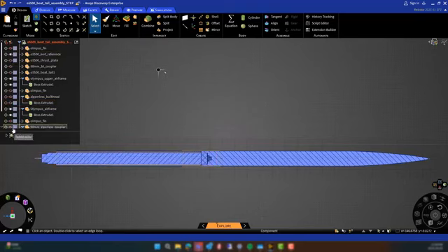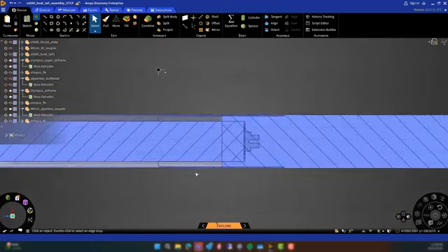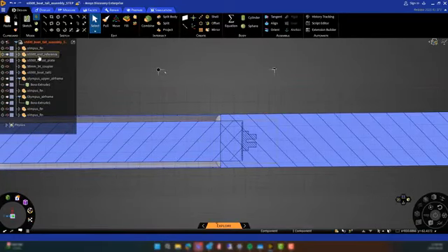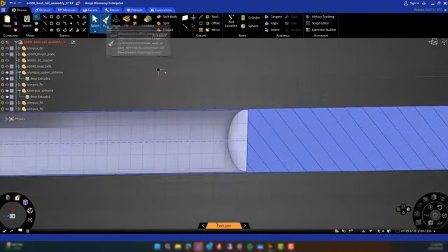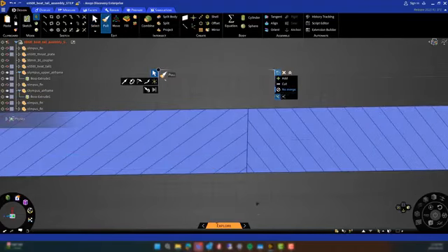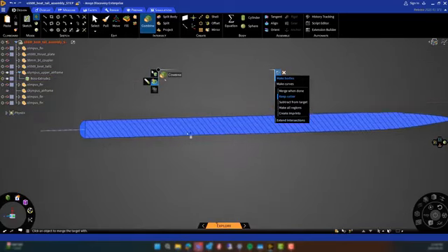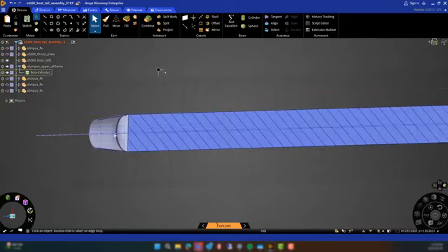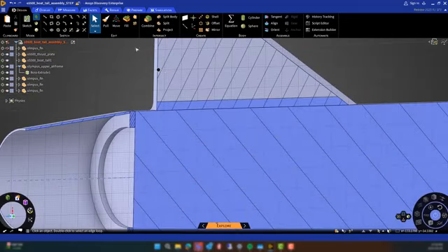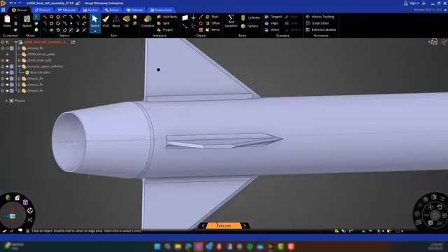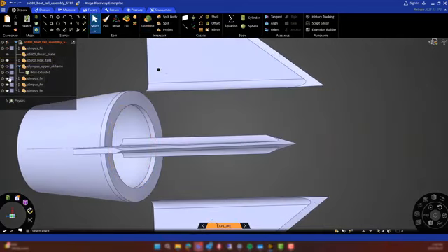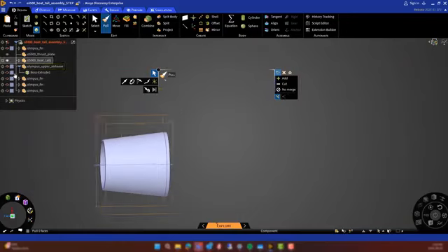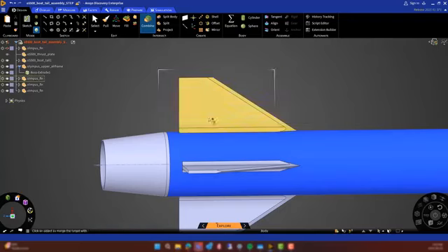As more parts are made visible, we can delete unnecessary parts directly from the object tree. The process of making shell bodies into a solid with the Pull tool, combining multiple bodies into one with the Combine tool, and deleting unnecessary components is repeated for the rest of the rocket. Throughout this process, hiding ancillary objects, changing the coloring of specific objects, and keeping a clean object tree helps keep the workflow organized.